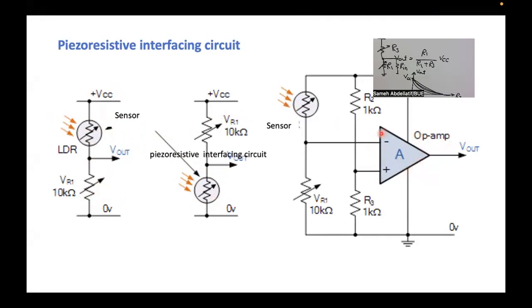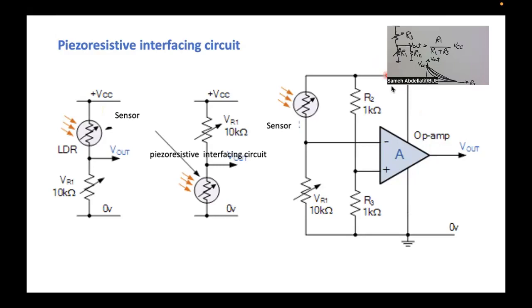Here, my dear students, we are using an operational amplifier. I think all of you are experts with this operational amplifier, and as you can see, it is connected with some sort of supply, so it has a VCC in the upper side, and then a ground in the negative side, and then we have these two connecting terminals. Usually, if one of these two terminals is connected to ground, that's a basic way to have a single mode amplifier. But now, when you have two different inputs connected to the inverting and the non-inverting terminals, that means you are connecting this in what we can call the differential mode.